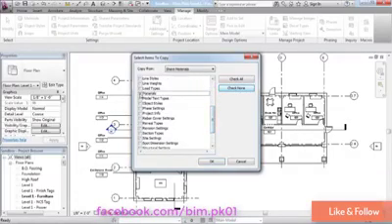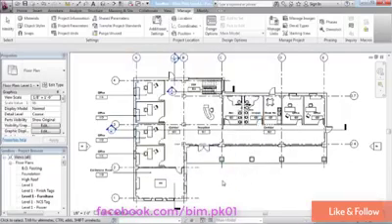Here's materials. It doesn't offer me the list of materials and allow me to pick and choose. So it's either all the materials or none of the materials. So I go from having a very lean family with just the 3 or 4 materials that it starts with to a family that suddenly has 200 materials when I only needed 2 or 3. Transfer Project Standards is not a great option either.